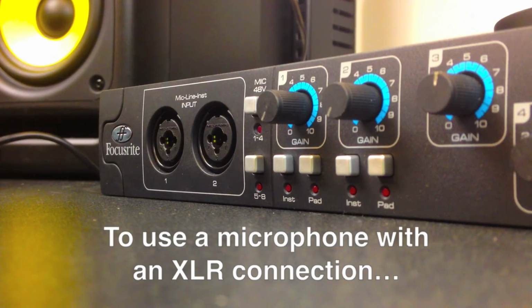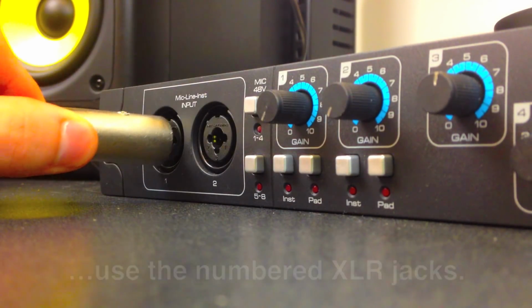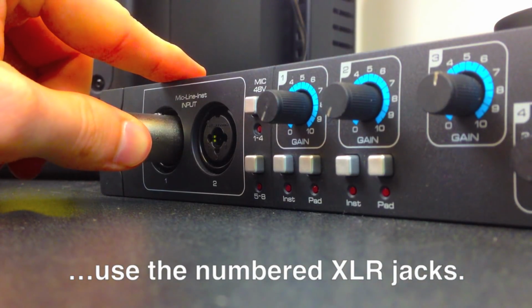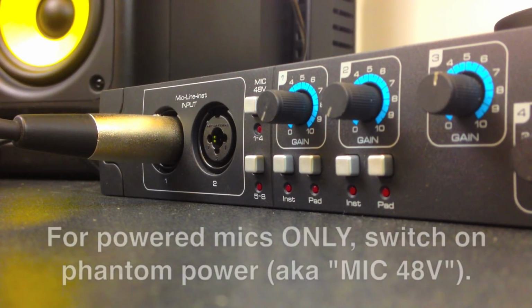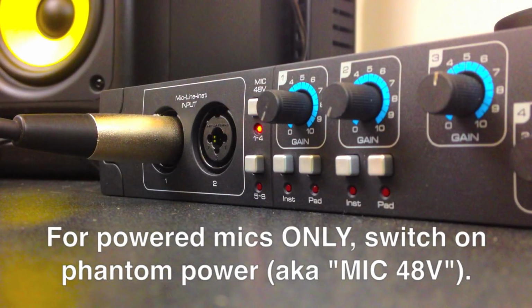You can plug microphones into the XLR ports on the front of the Focusrite. If you ever need to use more than 2 at a time, you'll find 6 more ports on the back. If you're using powered mics, activate phantom power with the Mic 48 volts button. The upper button applies to ports 1 through 4, while the bottom button applies to ports 5 through 8. If you aren't sure whether your mics need phantom power, leave it turned off until you can find out, because phantom power can damage certain types of mics.